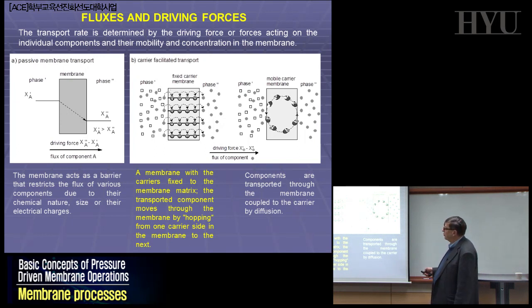And that's the configuration. We have a certain concentration of one component in our feed solution, and we will have a different concentration across our membrane, a concentration gradient here, and some of the species will go across. The concentration of species A in the feed solution and in the permeate will be different. That means higher concentration here, and if the membrane is doing the job, much, much lower here.